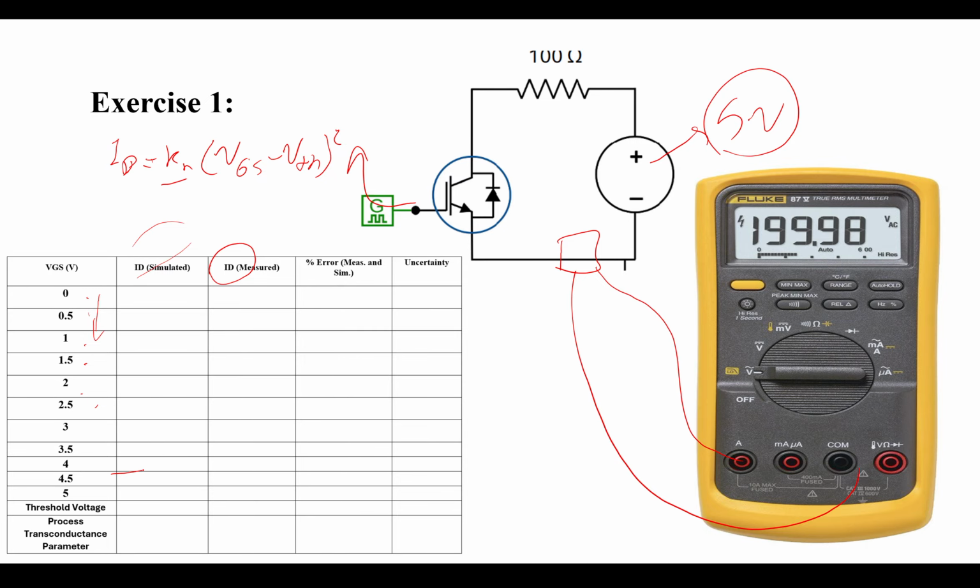So for example, here, you have the VGS, you have the current, okay? You know the threshold is somewhere between these values, okay? And then it's just a division, a very simple mathematical derivation. You find the Kn. Are we good?